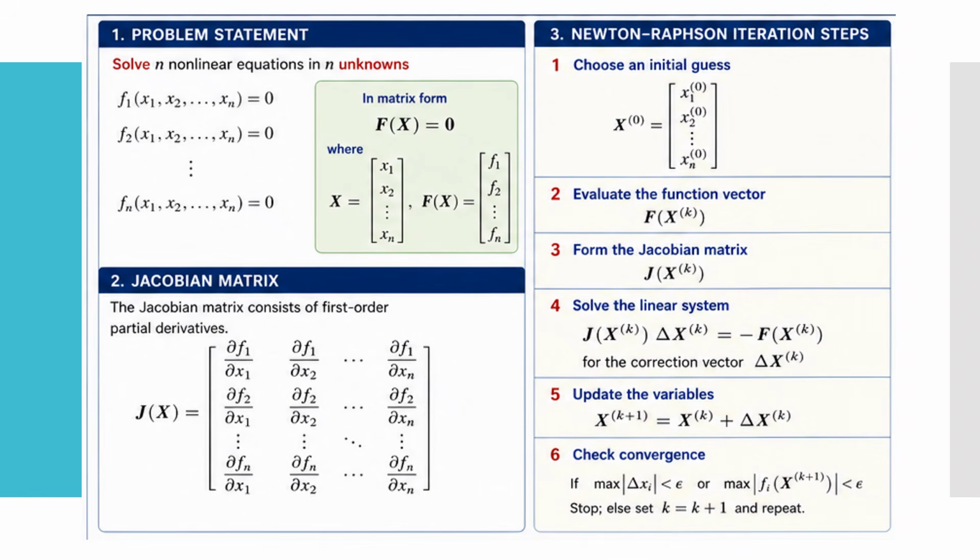The second method that we will use when we are doing power flow analysis is the Newton-Raphson method. The Newton-Raphson method is very suitable for a nonlinear system having n variables and equations. For Gauss-Seidel, we see that it's appropriate for a linear system, so that the iteration can be performed by deriving an equivalent representation for a diagonal variable and taking the iteration continuously. But when we come to Newton-Raphson, we'll use this for nonlinear systems.